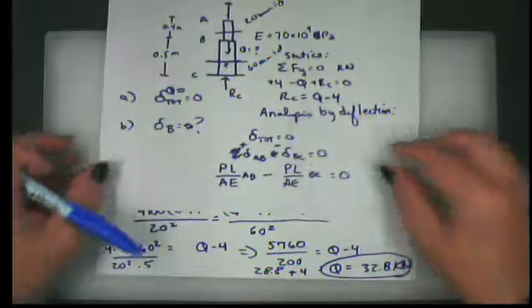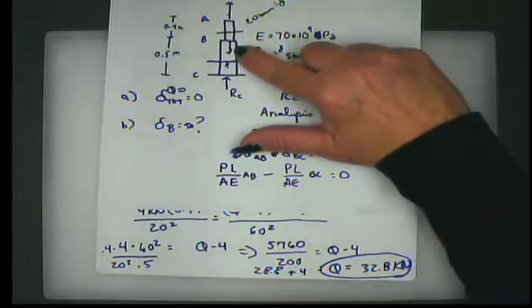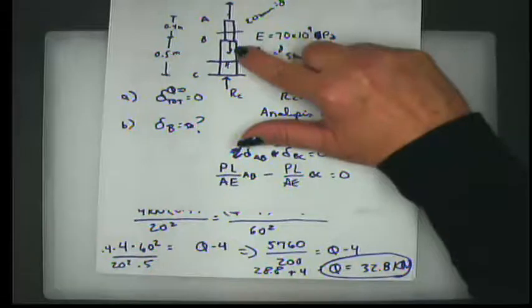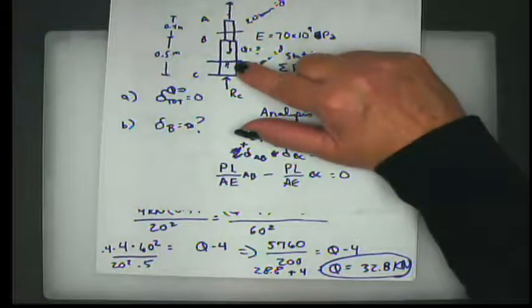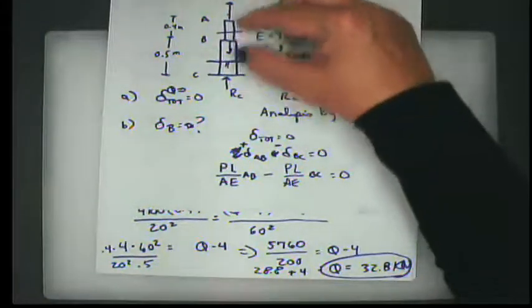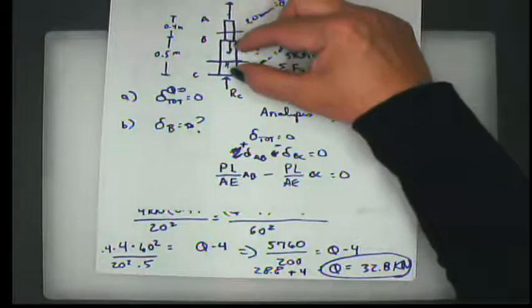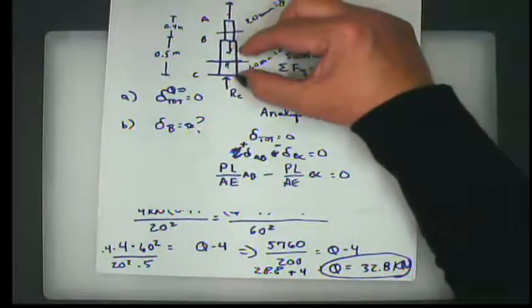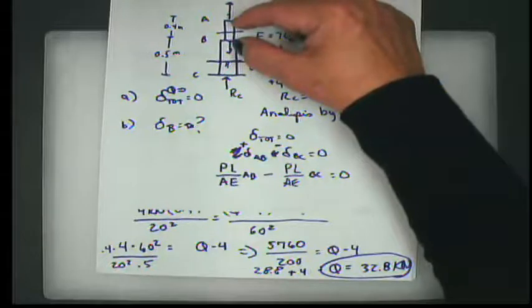Okay, so what does that mean? Well, this makes sense, doesn't it? I have to put quite a bit of compression on this larger joint in order that the compression here equals, not compression, but the shrinkage here equals the elongation here. Okay?